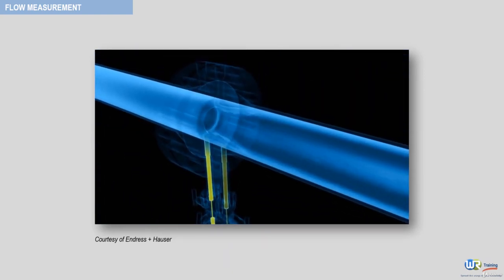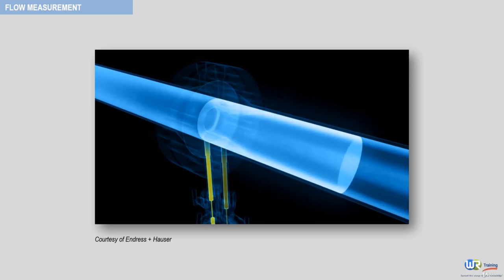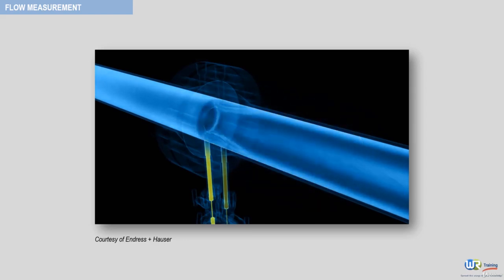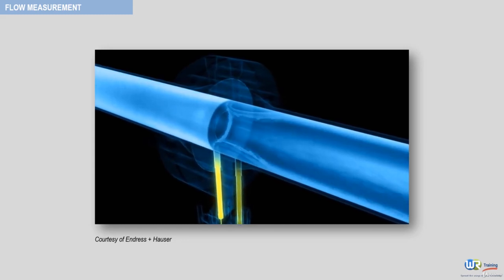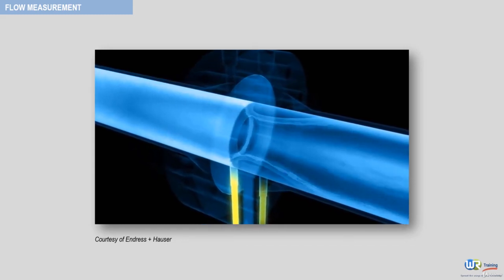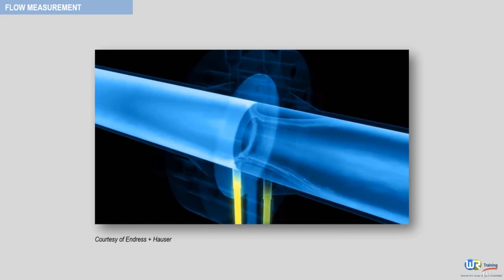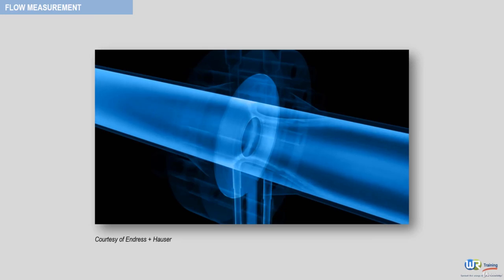This pressure difference is a direct measure of the flow velocity and thus the mass and volume flow in the pipe. The higher the flow velocity and the resulting drop in pressure around the orifice plate, the greater the differential pressure measured. In numerous industrial applications, the orifice plate covers many needs of flow measurement technology.